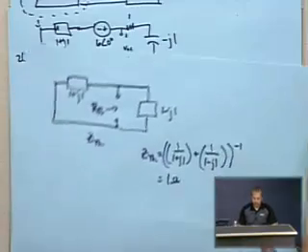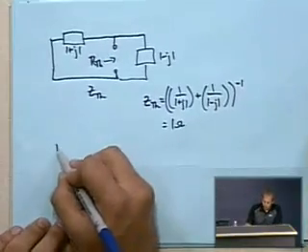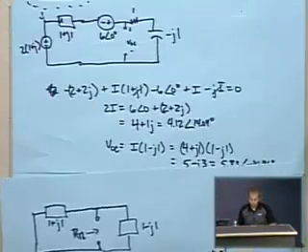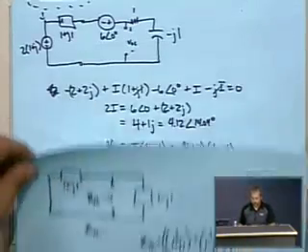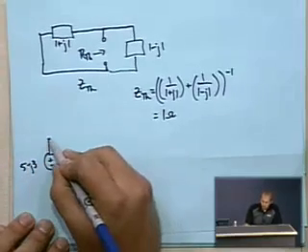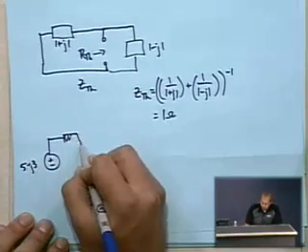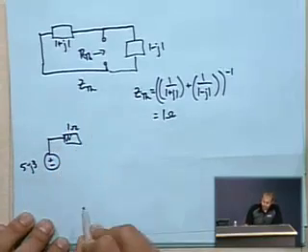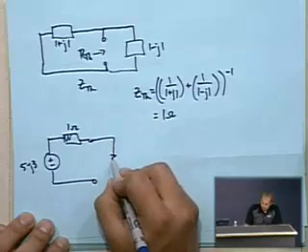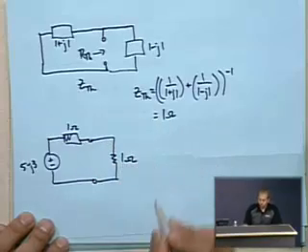So what we will have then is a circuit where we have a voltage source that is putting out 5 minus j3 volts. We have our Thevenin impedance, which is 1 ohm. And then we can hook our load back up, which was another 1 ohm resistor.